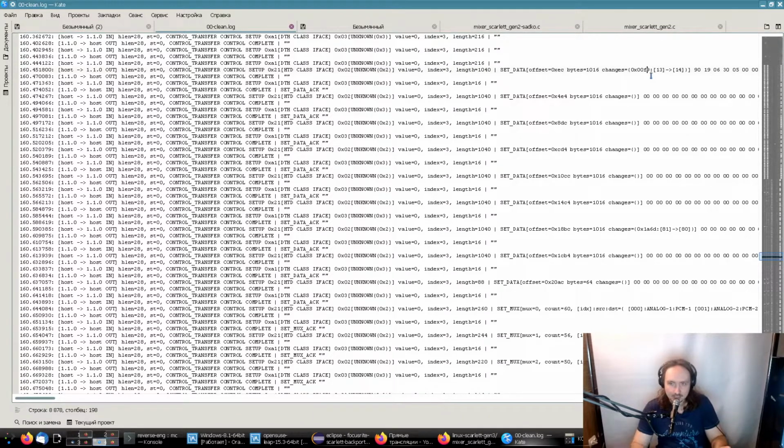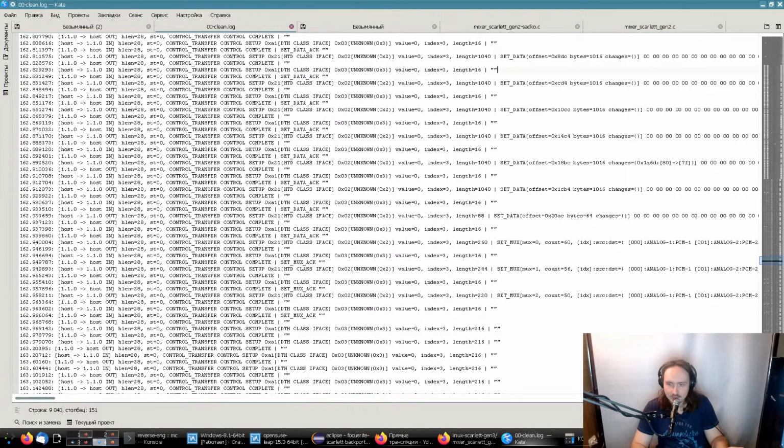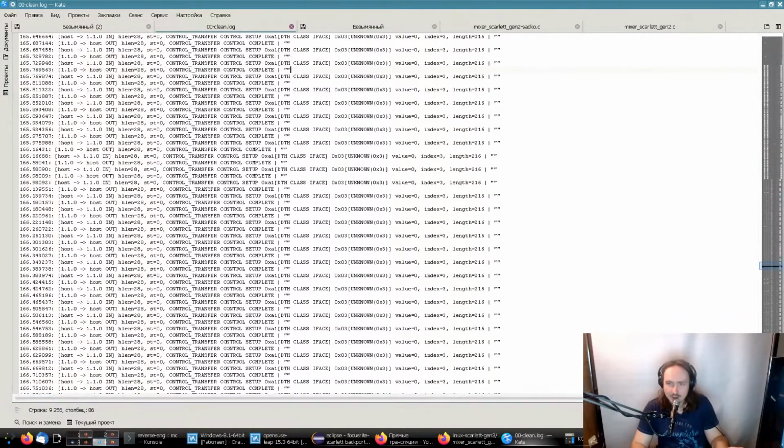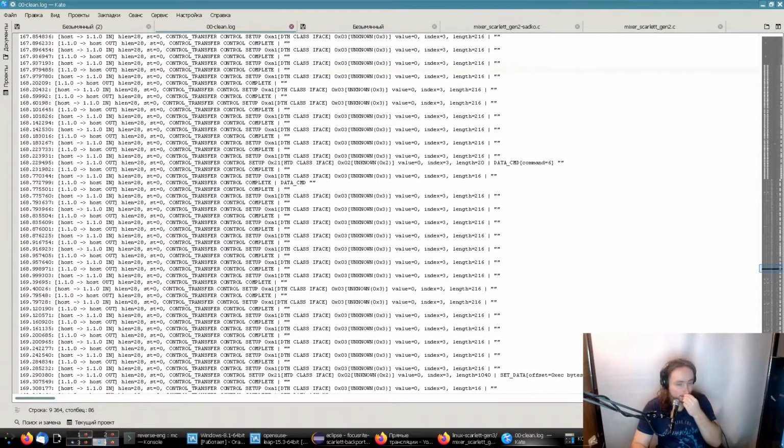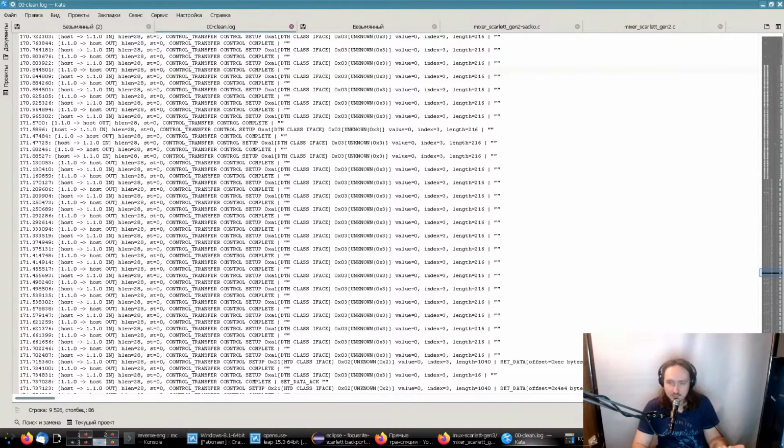So we have changed the same values, but the destination byte is F9. F9, F9, and so on. So at this moment, we can say that we have discovered the input port naming or numbering. We have discovered the bytes which are assigned to the output 1 and output 2 analog outputs.